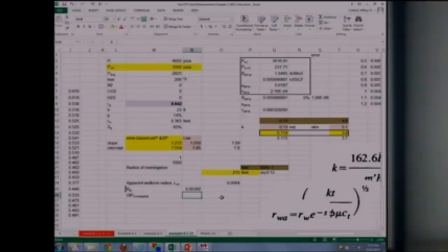Now, am I going to say gas in place equals 43560 SGPH over B sub G, or am I going to do something different? You have to calculate area from the radius of investigation. Or I can just leave the 43560 out. Why convert my radius to acres and then go backwards from acres to feet? Remember, everything's really in cubic feet. So my area is equal to what? Pi r squared.